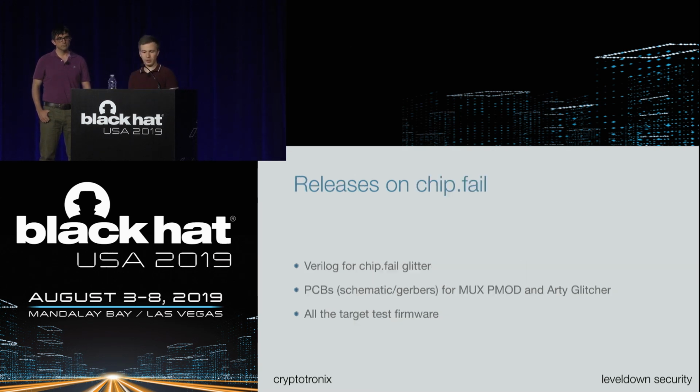Releases are on Chip.Fail. We'll release the firmware, or well, the bitstream and the Verilog for the Chip.Fail glitcher. We'll release all the PCBs we talked about, so for the MUX, for the RT glitcher, for the Trezor, and all the target test firmware. We also will release some tools for Ghidra to make boot ROM reverse engineering much easier.